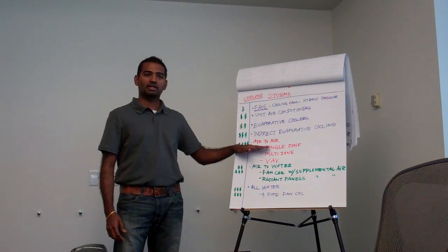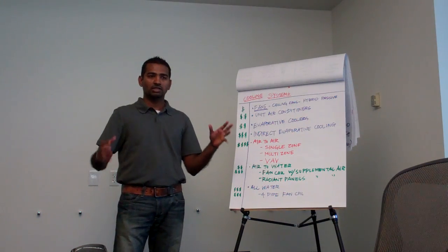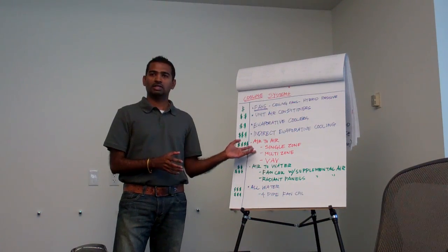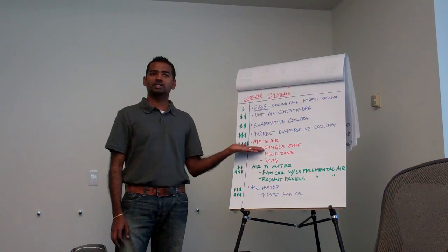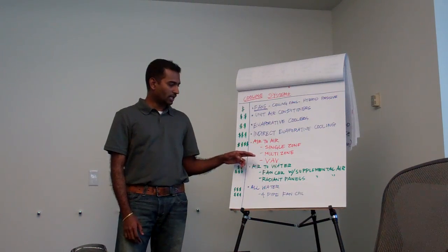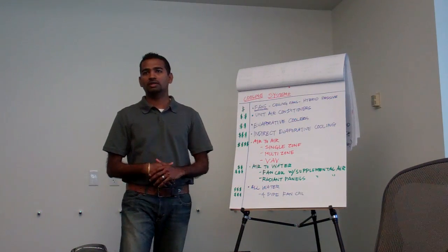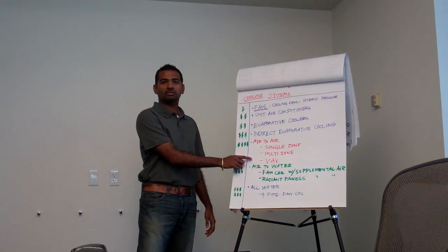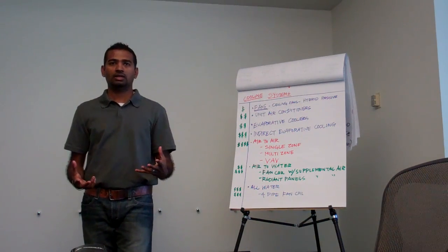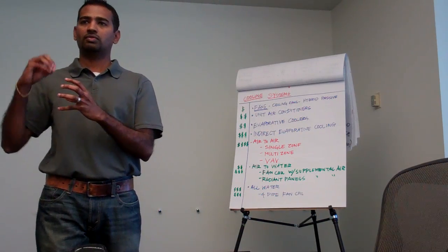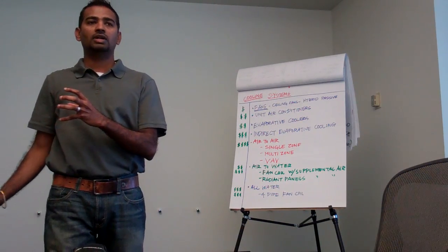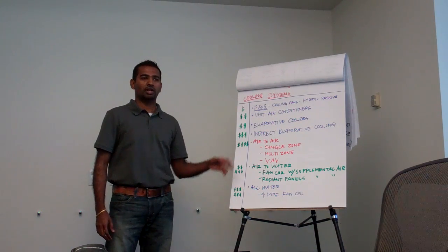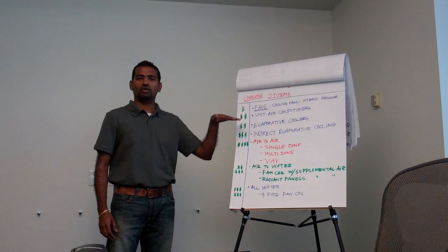Single zone is very effective because it solves the local need right away. But the problem with this is, I have 50 of these to maintain, as opposed to having one multi-zone VAV system. But the multi-zone or VAV system will have a lot of ducting because it's central and it goes from one place and covers most of it. So you need more room. So from a design standpoint, I think it's important to first figure out